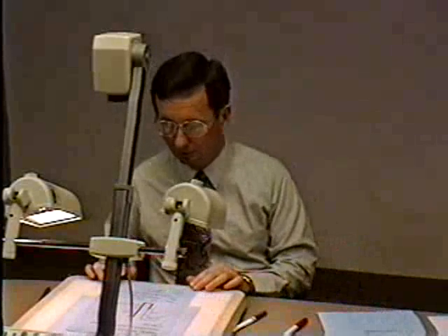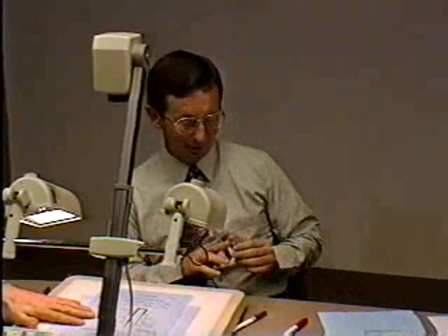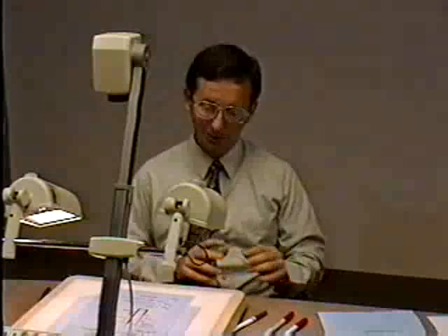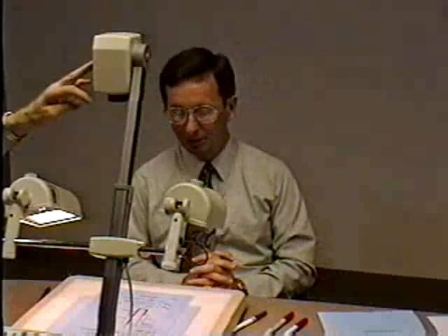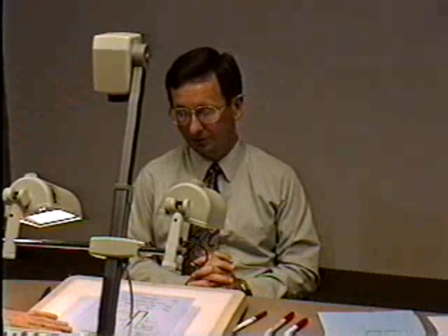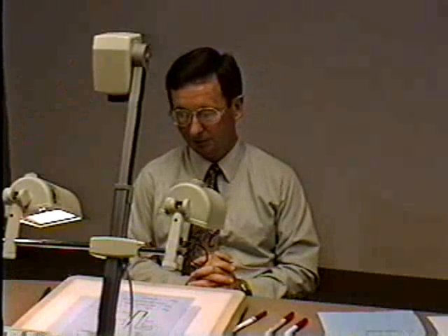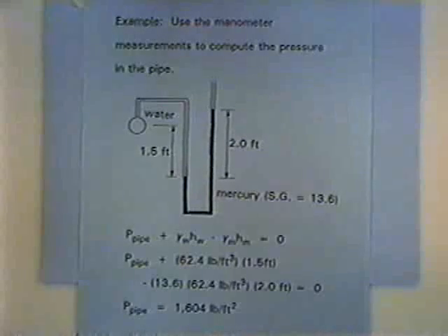And so if we repeat ourselves, let's express the same concept in the context of a manometer problem. This is another classic fluid mechanics problem of fluid statics that expresses the basic concepts, and in addition to expressing the basic concept that pressure is gamma times h, this also happens to be a measuring device. A manometer is a device that's used to measure pressures, a very accurate device at that.